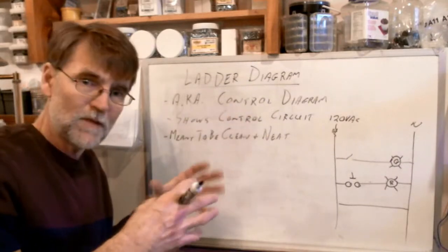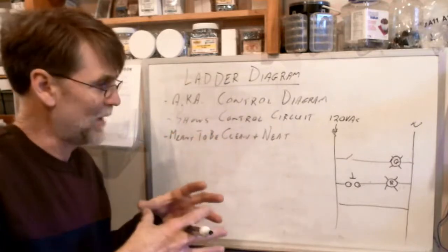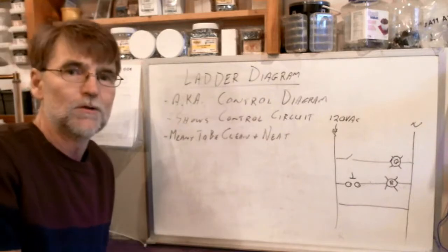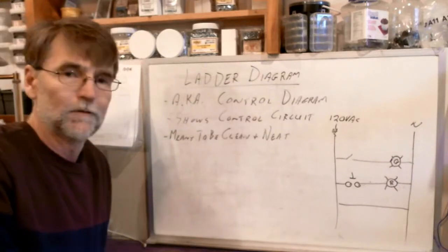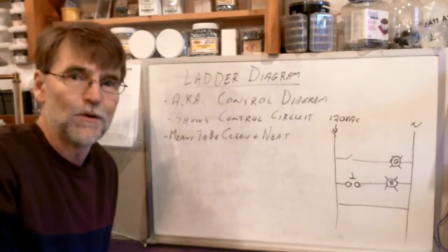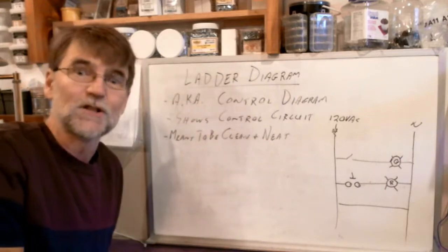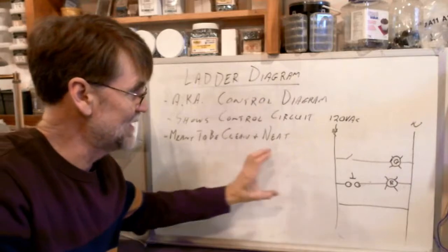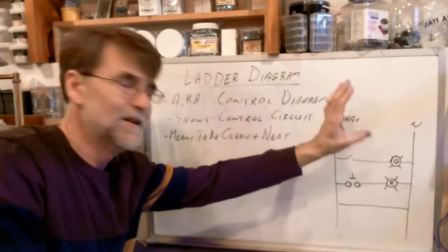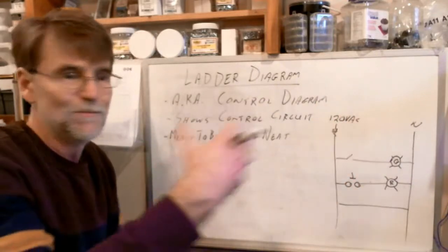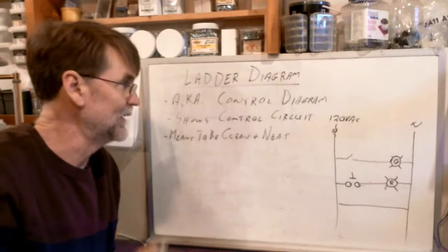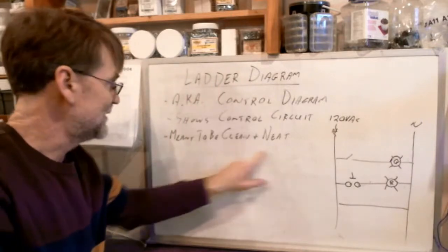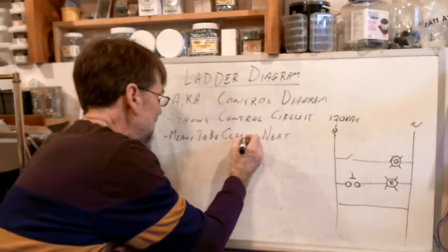Things don't start getting all jumbled together and crowded into one space. Every time we have a new idea, we build a new rung to our ladder diagram. I've worked off of ladder diagrams that when they are printed out, they're 80 pages long. Just keep adding another rung. It doesn't add any mess to the existing idea. We just get new ideas, move on to the next page and keep building, add another rung to the ladder. So it stays clean and neat.